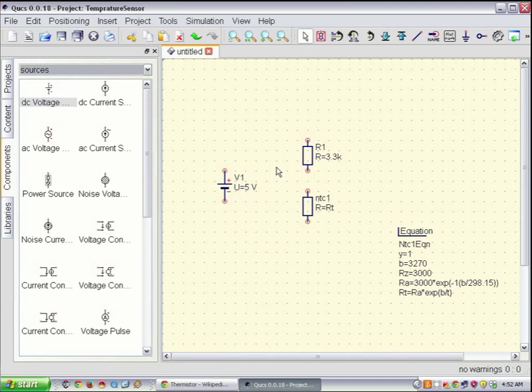Then we are going to add the ground for the circuit. So we'll select this insert ground. Keyboard shortcut for this insert ground is Ctrl G. We select this, position it. So you can have any number of ground symbols. They are all going to be the same. It's a copy of the same symbol. So this helps in reducing errors while wiring.